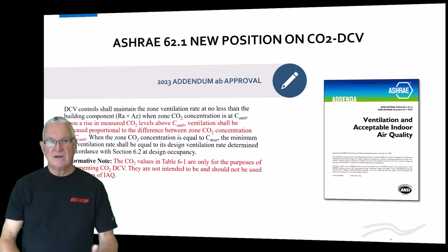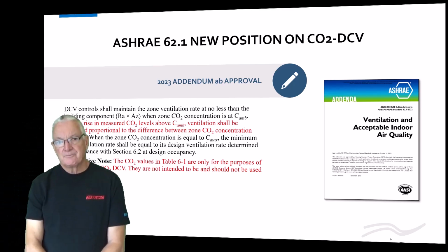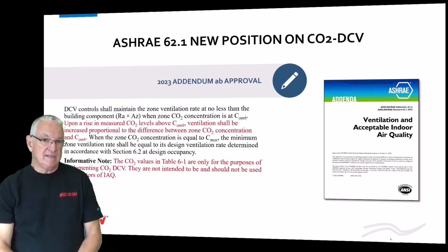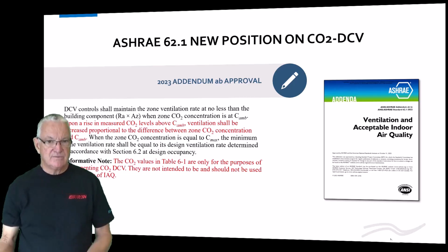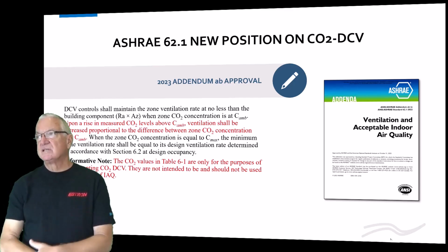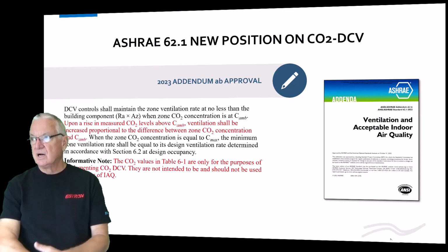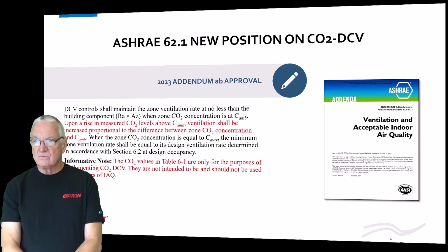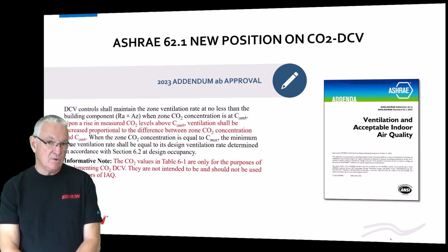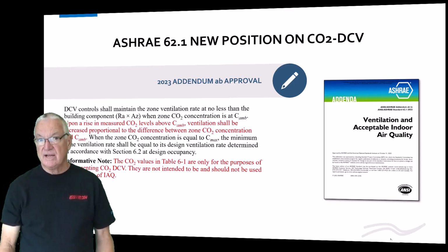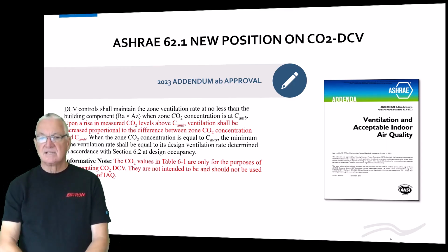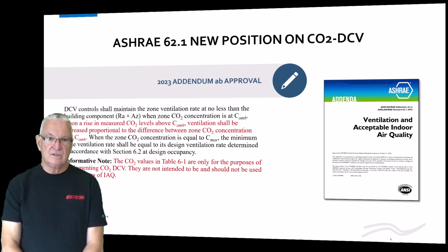Great. I should be running around pushing this. And I guess in a way I will be. Yes, the way you satisfy this is put a flow meter in and reset the outside air. There are problems with this whole strategy for multi-zone recirculating systems, but certainly on single zone air handling units or DOAS, single or multi-zone DOAS, this works great. Just reset the outside airflow set point based on the CO2 level.